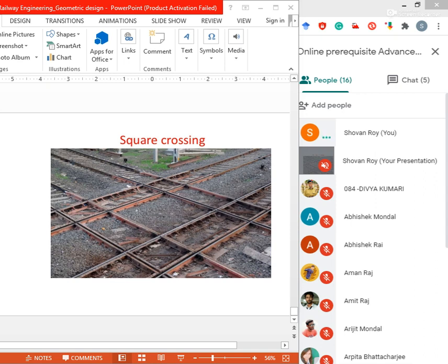Adequate land: there should be adequate land available for the station building, not only for the proposed line but also for any further expansion. The proposed area should also be without any religious buildings. Level area with good drainage: the proposed site should preferably be on fairly level ground with good drainage arrangements. It should be possible to provide the maximum permissible gradient in the yard.